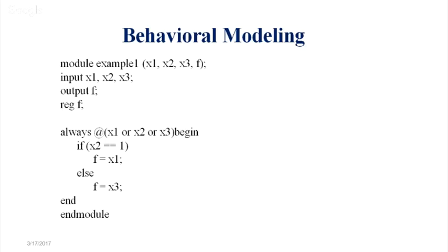Then you have to produce your own inductor and your own capacitor accordingly, because everything is associated. In the DC analysis of your DC to DC converter, the range of inductor and capacitor are all interrelated with the help of frequency. When I change the frequency, everything will change. The output may differ.